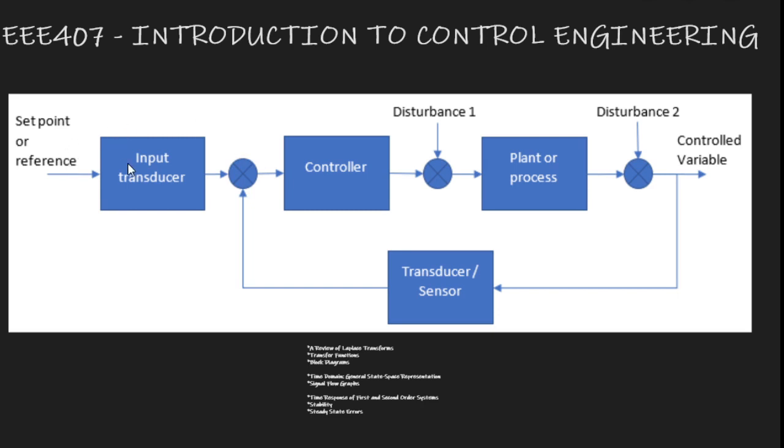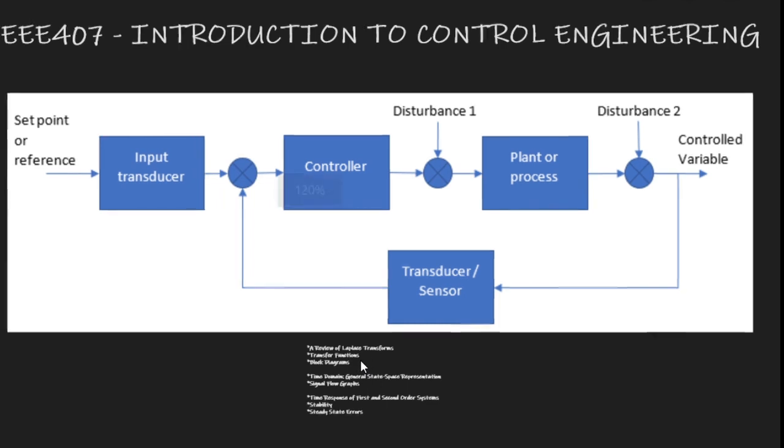So for the transfer function, we often will use G, or we might use T. In the forward part, for the feedback, we often will use H. So if we use T here, then we simply say U times T will be equal to Y. Okay, U times T is equal to Y. So the input times the transfer function is simply equal to the output, and that's the beautiful thing. So that's why Laplace transforms are very important.